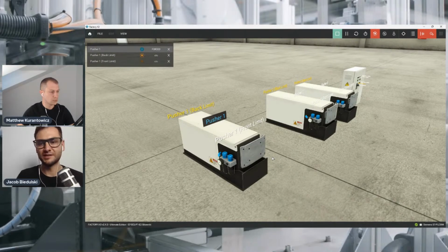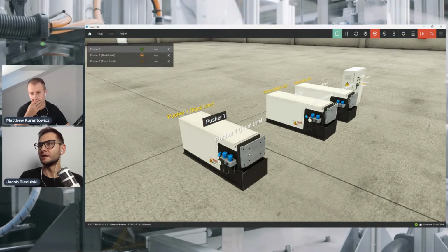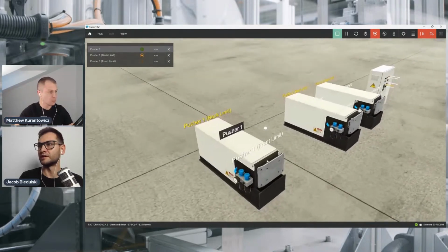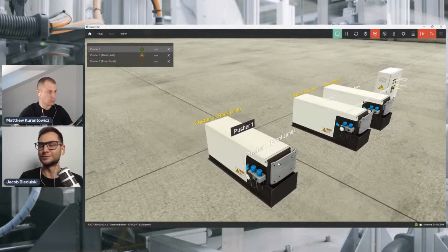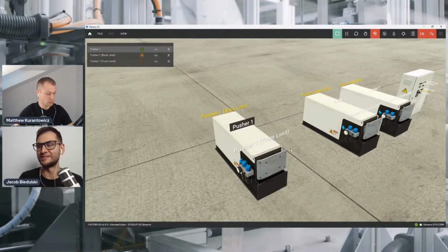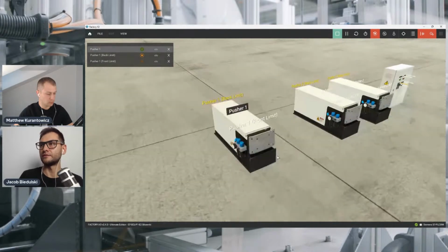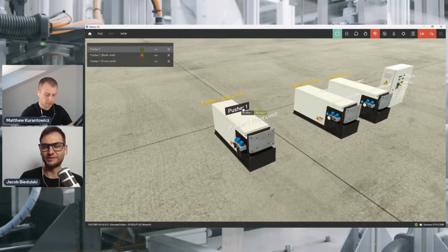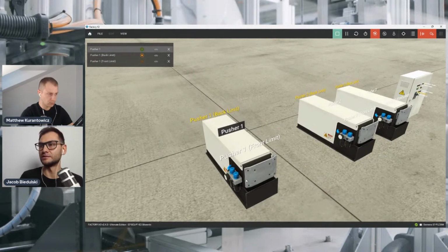So generally a simple device. It is commonly used in many automation systems because it's really simple to control. You don't need some extra numerical control systems or controllers for those actuators. You have one coil or two coils. It depends on the valve that is used to control this actuator, and usually two sensors.